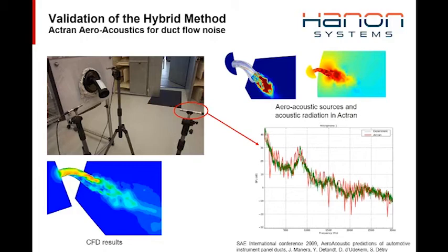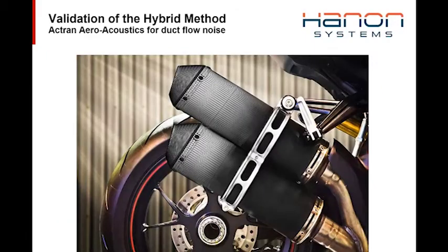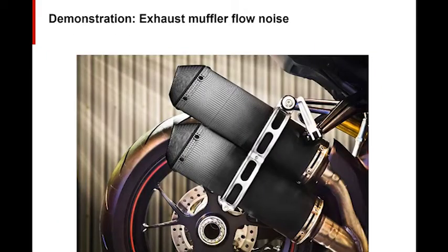One, establish the mesh resolution for acoustic analysis, and establish the time step we want to use for transient simulation and all these things. So the steady state simulation we do is the main basis for the future simulations we do for aeroacoustics. Once that part is done, we do the initial transient simulation where we clear the initial turbulence, which is generated by numerical error or anything. And after we finish the first transient simulation, the final transient simulation is the one where we generate the samples, which we're going to use for acoustic sources prediction.